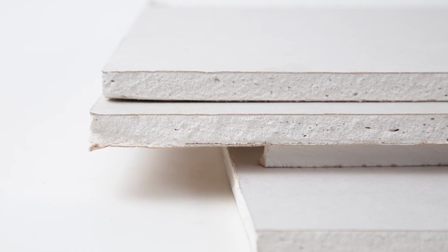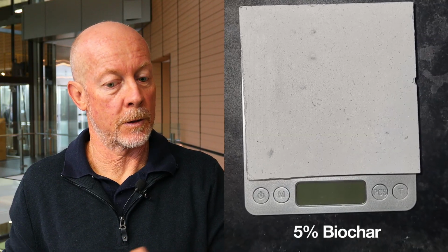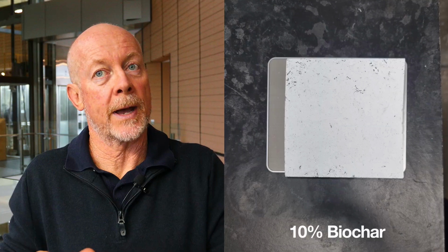And then we're looking at ways that we can capture carbon dioxide which don't rely on using existing chemicals, such as sodium hydroxide, potassium hydroxide, which themselves, when they're manufactured, have a significant carbon footprint. So we identified that in some of our earlier techno-economic and LCA life cycle analysis studies. And then also looking to introduce biochar into the final product and seeing what impact that has on the formulation of the product, and also the existing properties when we're looking to, say, apply it as a construction material.